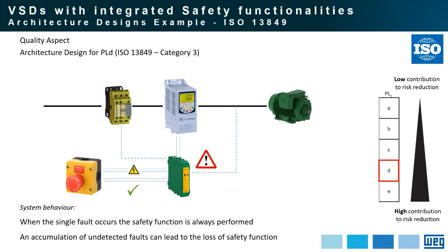In the power line, additional protection must also be considered, because in case of any problem with the variable speed drive, other components must be available to protect and to switch off the motor. So that is the reason to install the safety contactors. If the variable speed drive has a problem, the contactor will switch off the motor safely. And it happens as well the other way around. If the contactor has any problem, the variable speed drive can stop the motor safely.